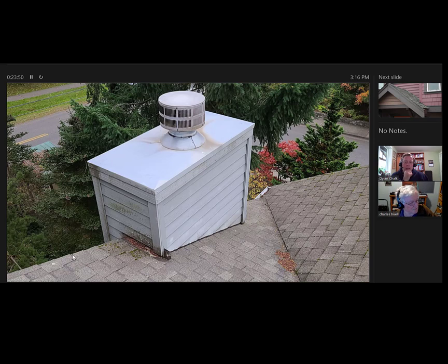Exactly. I've always felt that a sequence of a couple redirect flashings would really help to push water around that chimney and back onto the roof. We want the water ending up in this gutter, but that can be tricky, and I don't often see a redirect flashing here.